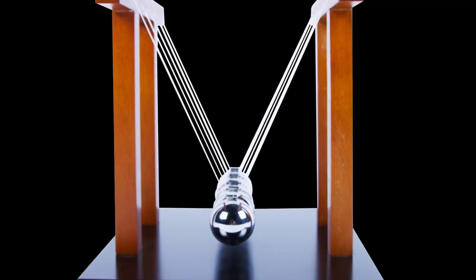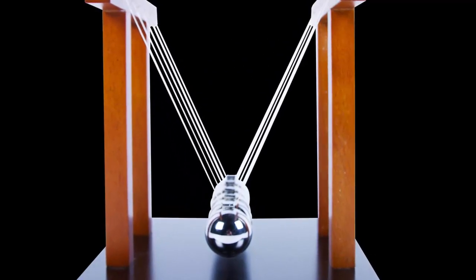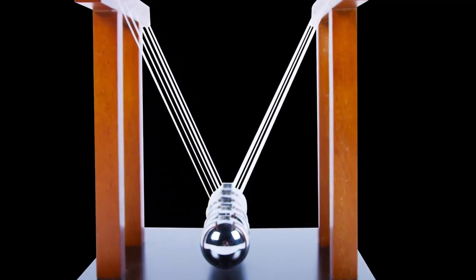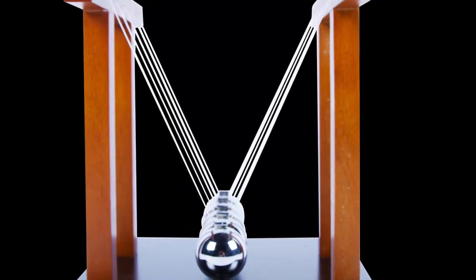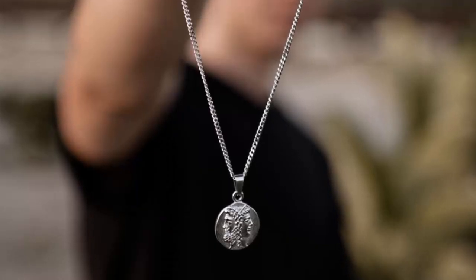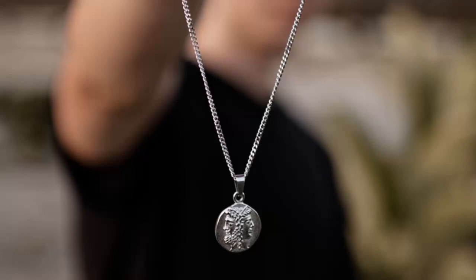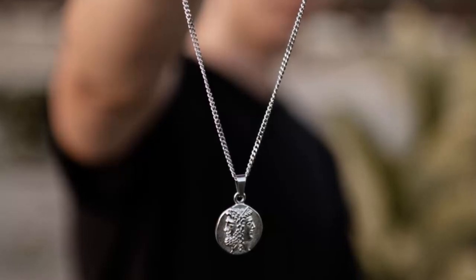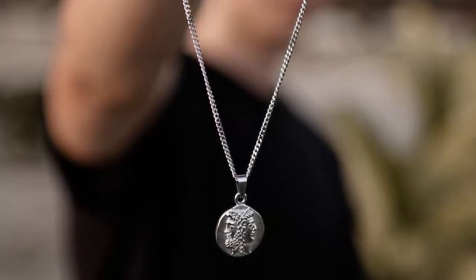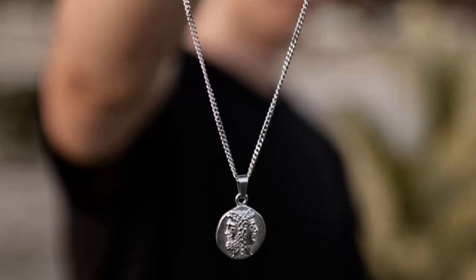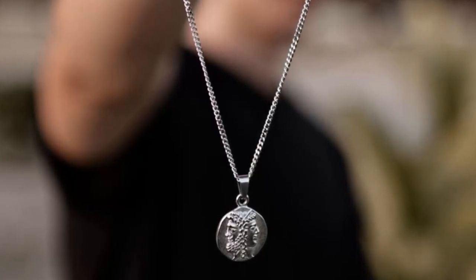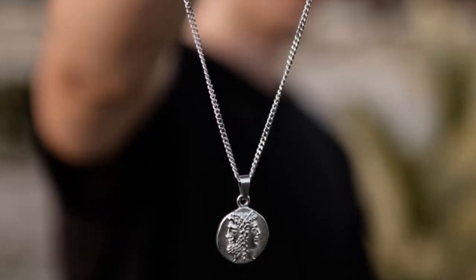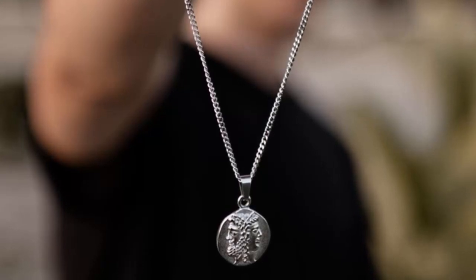This triangular profile is indeed what we see when the load acts on an element that is relatively light compared to the load. An example of this is a pendant on a necklace. But while in a physical scenario, the triangle points downwards, this is considered a positive curve according to the sign convention, and the bending moment diagram is represented by a triangle in the positive upward direction.